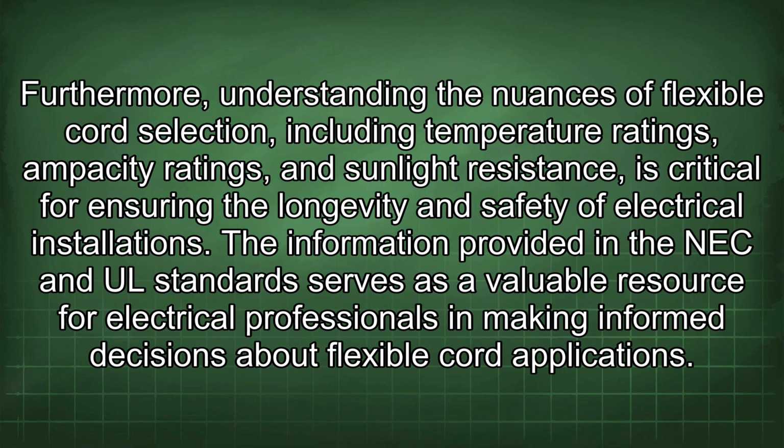Furthermore, understanding the nuances of flexible cord selection, including temperature ratings, ampacity ratings, and sunlight resistance, is critical for ensuring the longevity and safety of electrical installations. The information provided in the NEC and UL standard serves as a valuable resource for electrical professionals in making informed decisions about flexible cord applications.